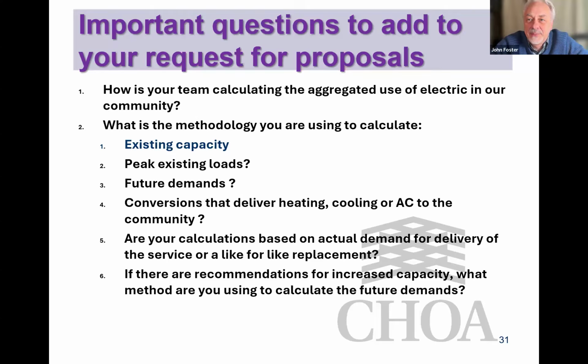That's the big question. And the best answer is that they would put a meter on your building, but very few people are doing that. It's kind of an extra cost, but if you can get an electric meter added to the building that measures the entire electricity and the peak power, it'll be very helpful. More typically, if it's BC Hydro, the consultant will talk to them and get those records, and they will get the annual profile of every hour, with the consumption from all the suites added to the main meter.